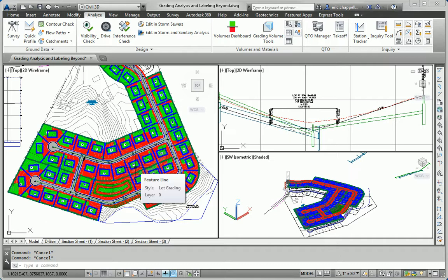of the road. Then after I did that, I would go back through and adjust the lots, get the building pads lowered down so I don't have any excessive slopes, and then eventually everything would be working properly. The lots would not have slope problems. I'd have closer balance with cut and fill, and my roads would be good as well. It's definitely an iterative process. It's a lengthy and complicated process, but that's design.